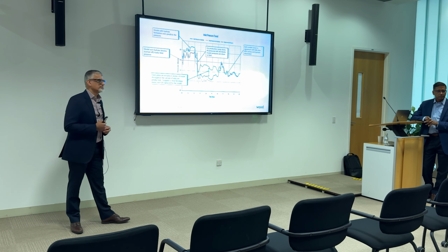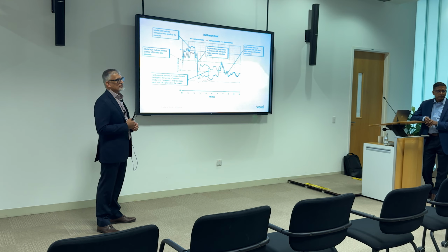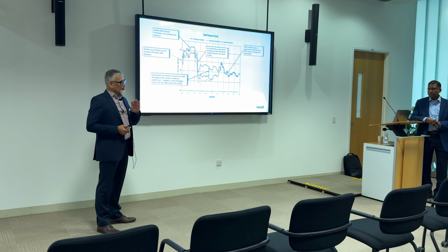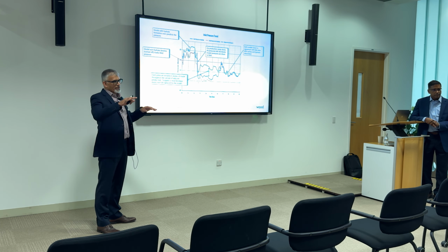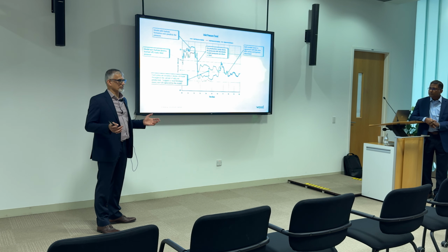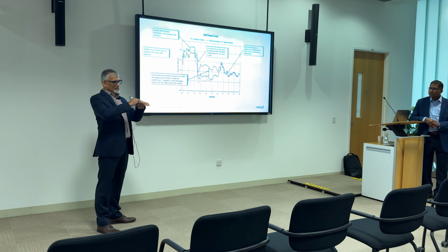And usually, Mr. Ashfaq, when you tune the model, does this last in the future, or another condition will form and you have to go back and tune it again? Based on your experience. So the only time you'd have to retune the model is if something has changed. So it will match, you get water breakthrough. As soon as you get, say, water breakthrough, all your temperatures spike and you see, wait a minute, I was matching temperatures exactly.